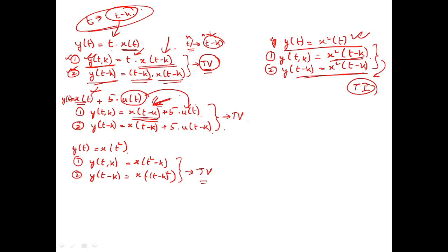It is not a, it is a signal. It is not an input signal. Okay. So since it is not an input signal, it will remain as it is. Whereas in the second case, where t will be replaced by t minus k, in all the cases it has been changed, and due to this reason 1 and 2 both are differing, and hence this system is a time varying system.